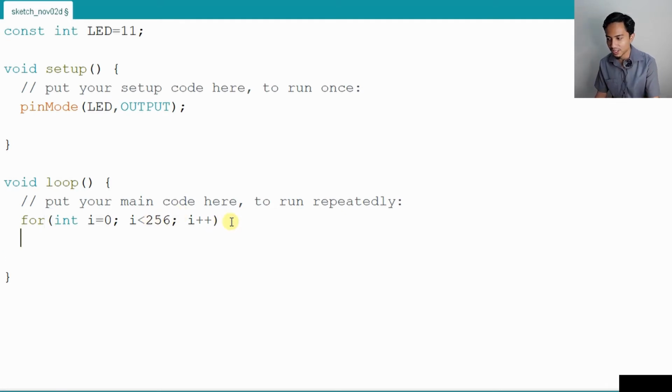So now here is the loop that we will use. What will be in this loop? As long as it is in this range, it will output the value on our LED, which means we want to write this data to the LED. But we can't use what we used before, digital write. Remember, don't forget that these lines are case sensitive, so don't use all small letters. If you use small letters, it cannot recognize them, so you must follow the code 100%, because it is case sensitive.